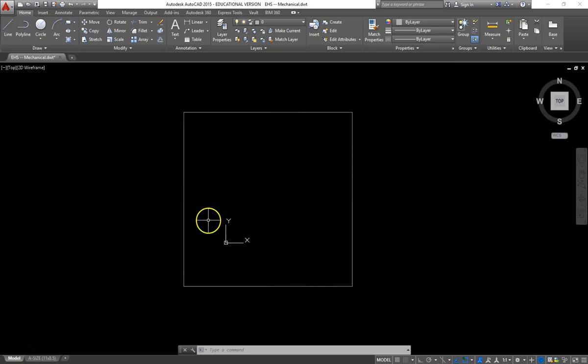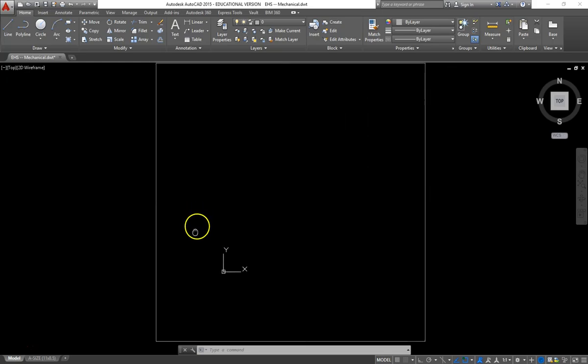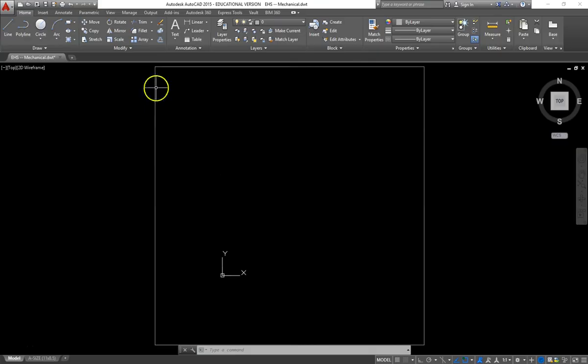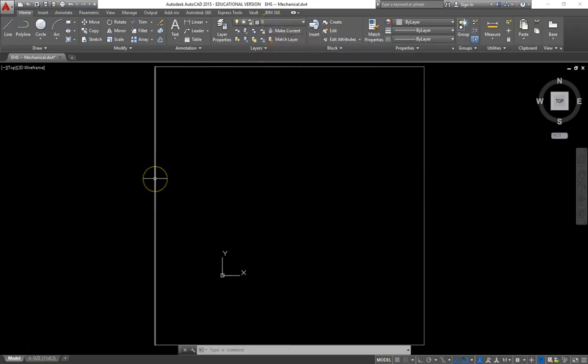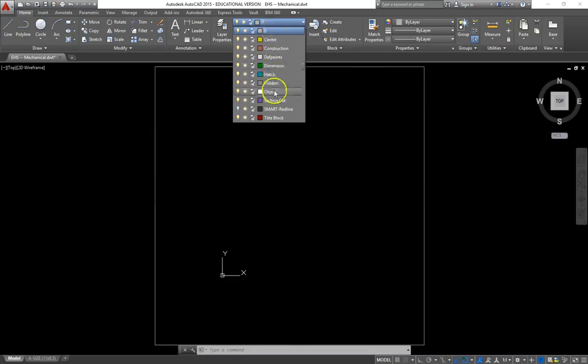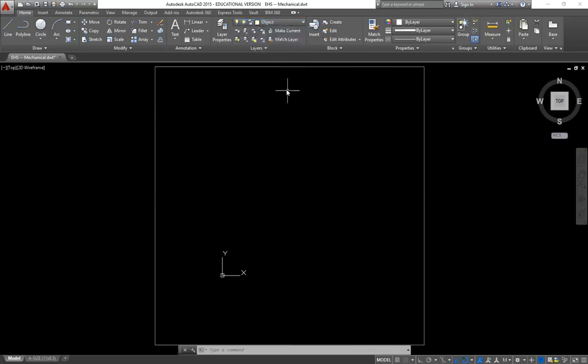So most drawings that we complete will be drawn inside this box and model space, which is drawn on the Zero layer. Now, if we review from last unit, we will remember that Zero layer will not print. So this box will not appear on your final drawing. Okay, to begin drawing, we will always use the object layer to draw all of the lines that have to do with our object. Hence the name object.